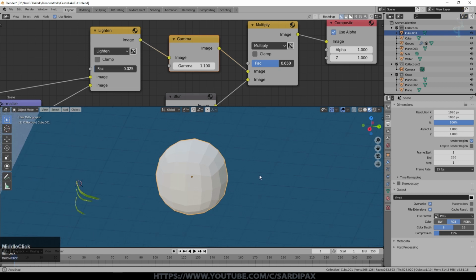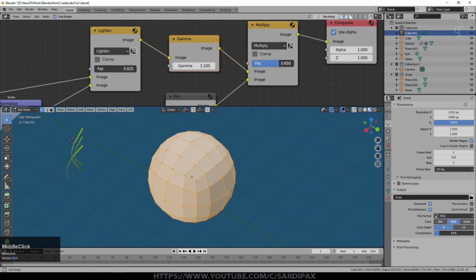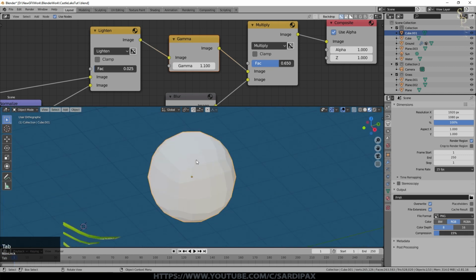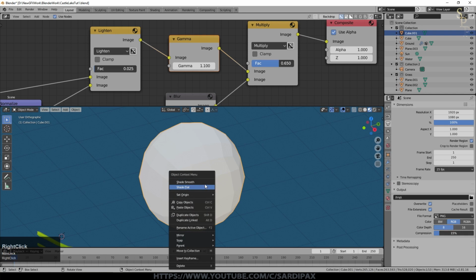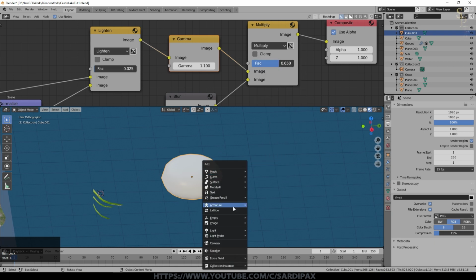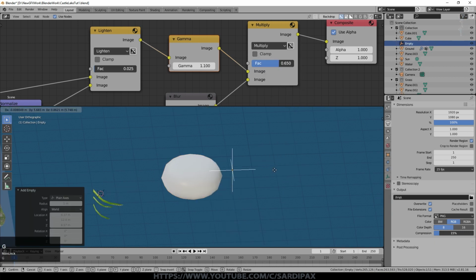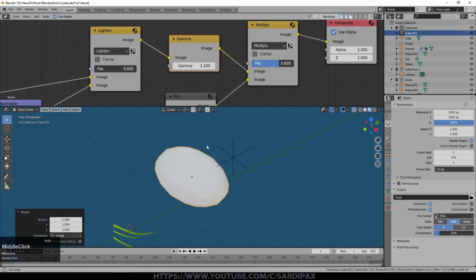Now you particularly want to do this if you want to keyframe animate shapes, because it gives you nice little quads for everything. They're not completely undistorted, but there's no point where lots of vertices come together. You've only ever got 4 connections to each vertex. We want to right click and say shade smooth, obviously. And now I'm just going to flatten that rock a little bit, and then I'm going to add an empty. This is just another quick and dirty way to create some variation. I'm making that rock a little longer there.